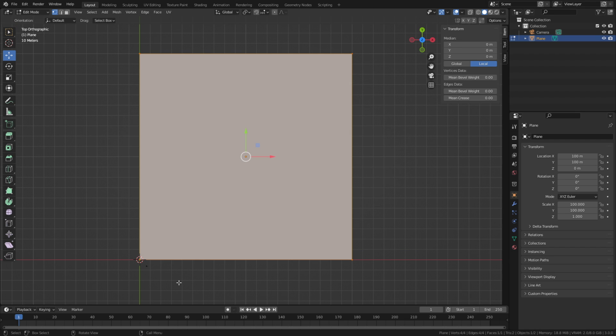All right, so the next thing we need to do is I want to create the 0 point on this height map. If you don't create an area that is at 0 meters, or if your whole height map is based at 0 meters and you ride on it in game, you get these things I call terrain spikes. That's when the deform is trying to happen, but you're at 0, it can't deform down, so it does some weird things and it creates these spikes that shoot out of the ground. And that's just happening because it can't deform down anymore.